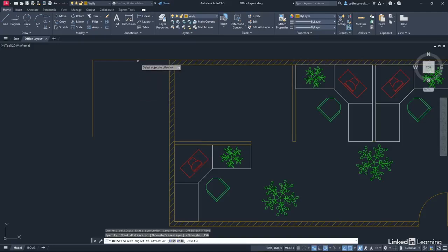So hover over this line. You'll see it highlight. Left click on it. Move downwards. Can you see that? And it's lining in with the rest of the wall. If you go upwards, it's not going to line in. So downwards there with the mouse, left click. You then select the vertical line, left click on it, move inwards, not outwards. Can you see it doesn't align otherwise? And left click again, inwards. Press enter to finish. You've now drawn part of the bin store for your office building.